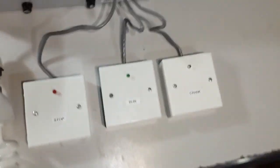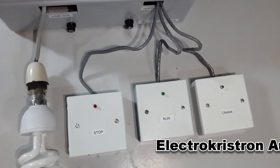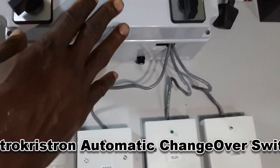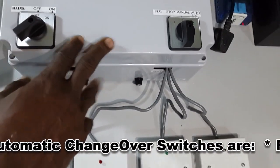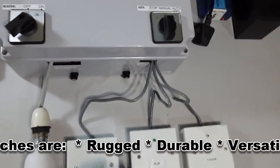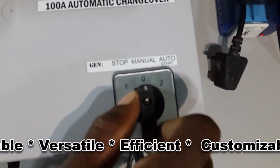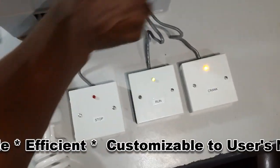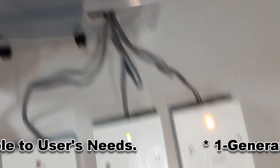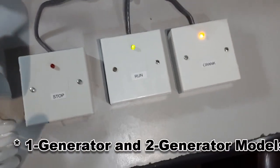But before we do that, let's take a look at the indicators again. You can see none of them is coming up, which means that at the moment no command is being sent from the changeover to your generator. Now the moment you put the switch on AutoStart, see what happens. Okay, the switch is now on auto. Two commands out to your generator.